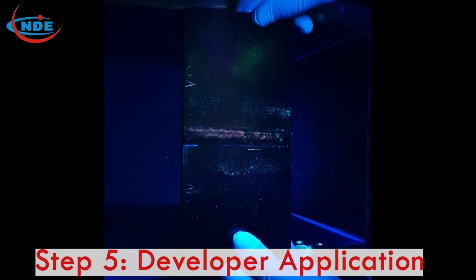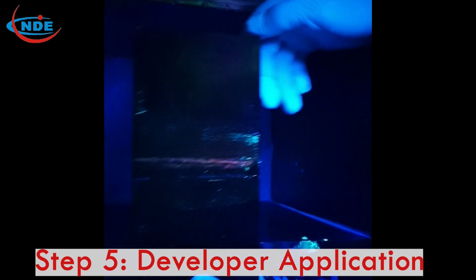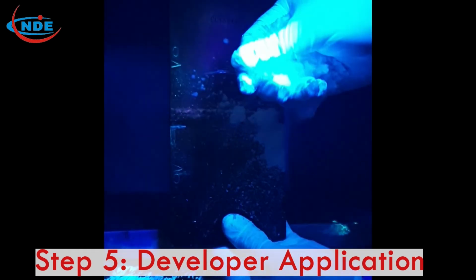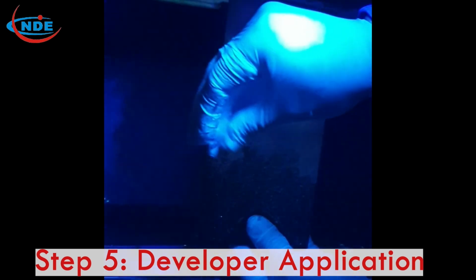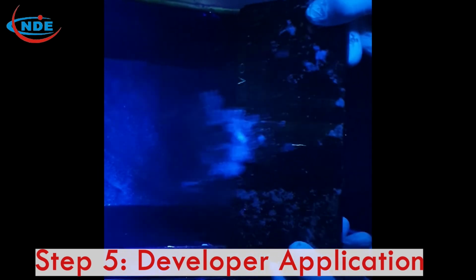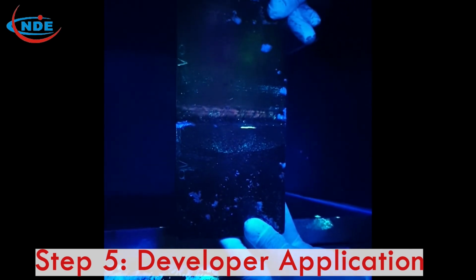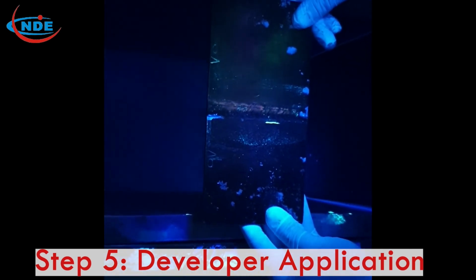Step 5. Developer application. Dry developer powder should be applied only onto a dry surface by hand powder pump, powder gun, or other means. Apply evenly the powder layer on the testing surface. The developing time is recommended about 10 minutes or maybe longer depending on the application procedure.